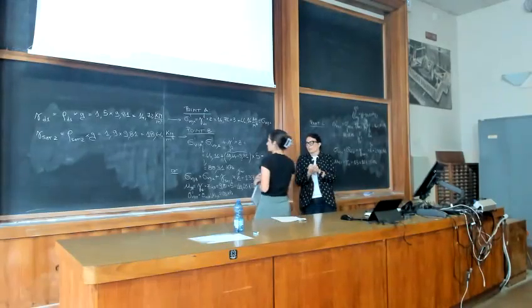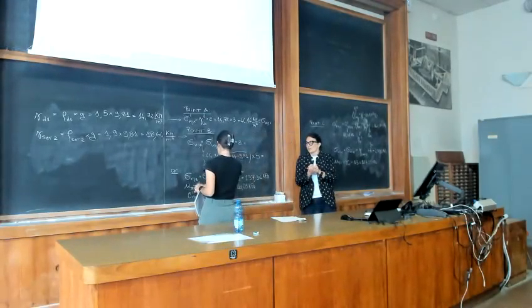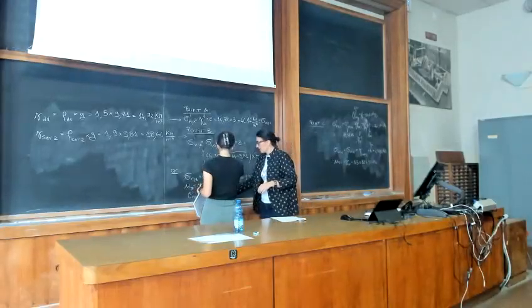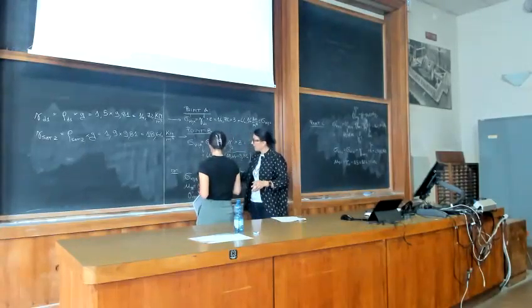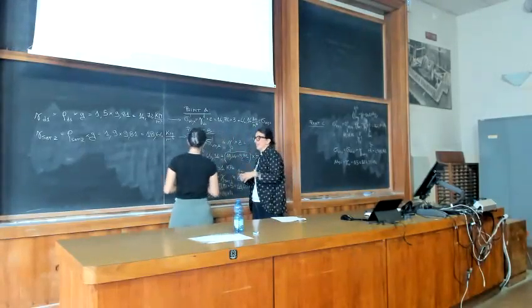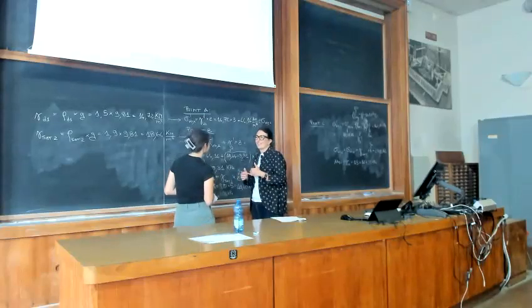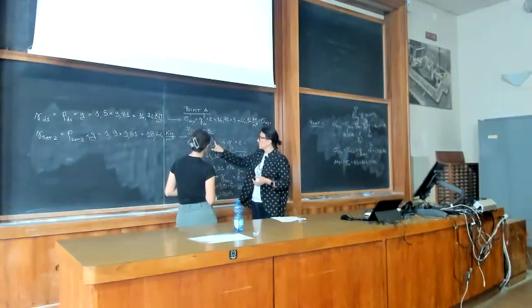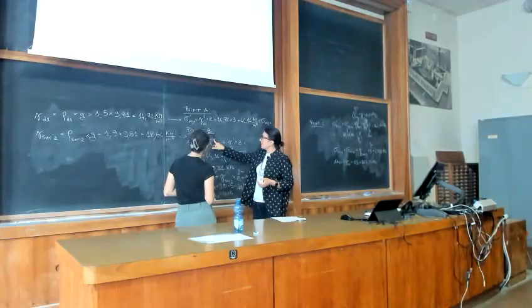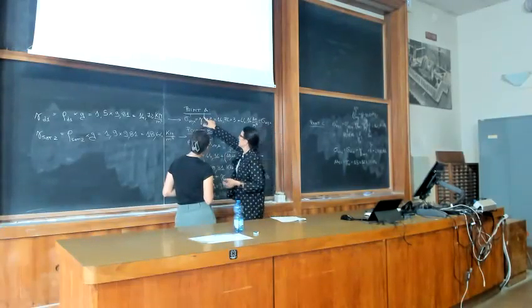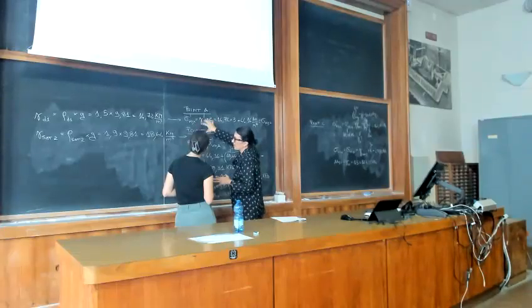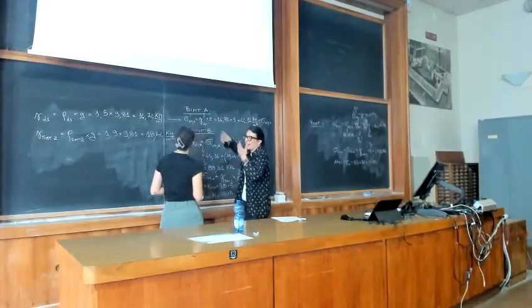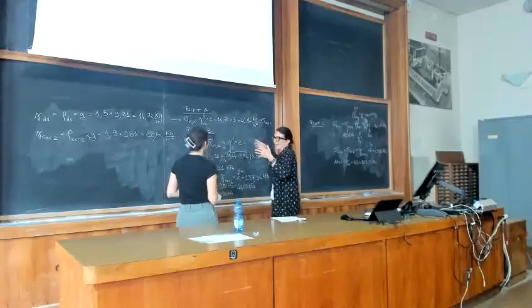So we've got total stress here, and then we've got pore pressure, and then you subtract. Or when we do it in a quick way, when you get practice on that, you can also directly calculate the effective stresses by using gamma dash. Here the soil is dry, so it is something different, because when soil is dry, total and effective stress are the same.